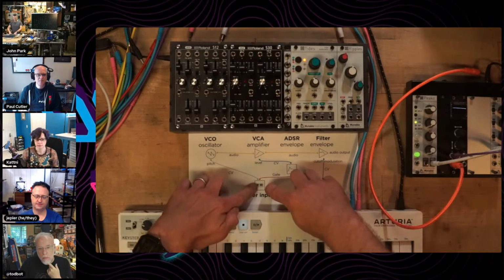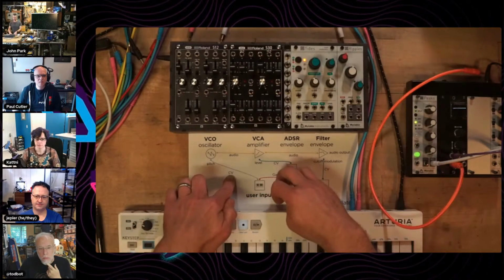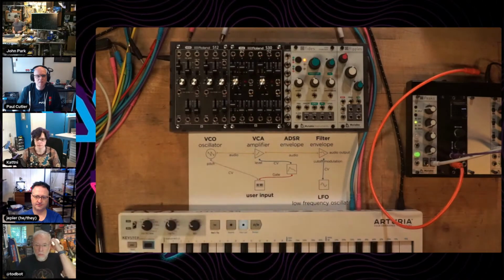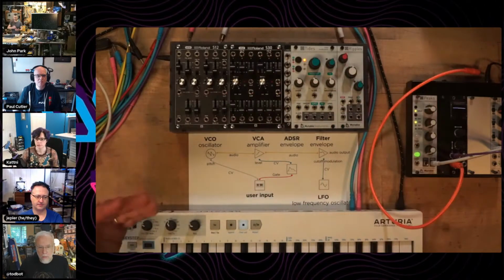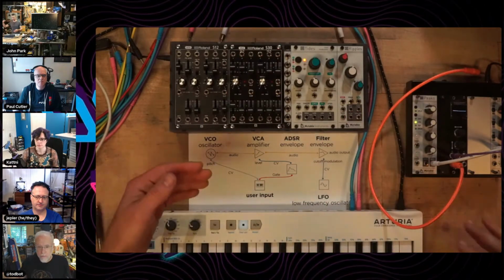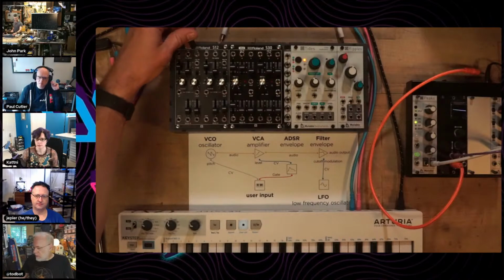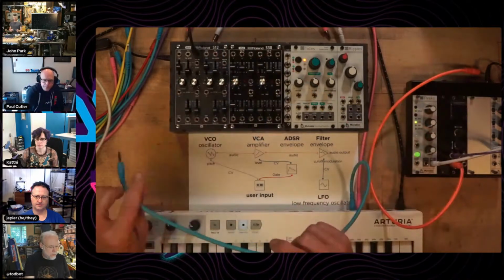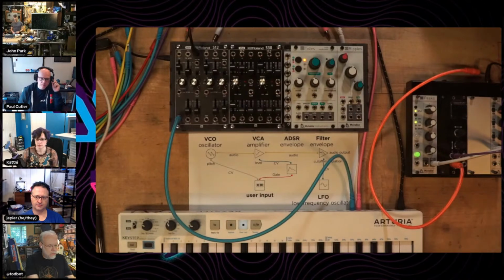And the message that is sent is voltage. So you see here CV, control voltage. And up here, it's kind of inverted, voltage controlled oscillator. So I'm going to send 1 volt, 1.5 volts, 2 volts, and so on. Actually, this system is based on a volt per octave. So I can jump an octave by sending 2 volts, 4 volts, or 3 volts, 4 volts, 5 volts, and so on. So what I'll do is give us that same output, but now I'm going to tell my keyboard to send voltage depending on what note I play.